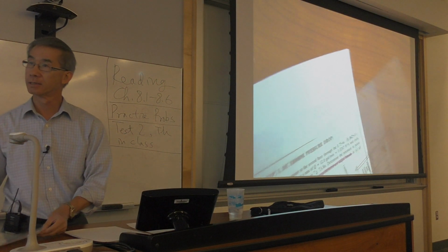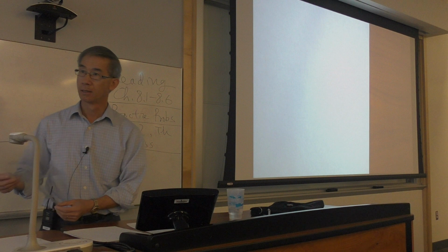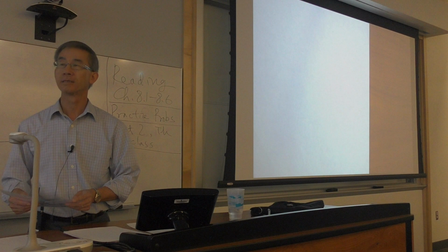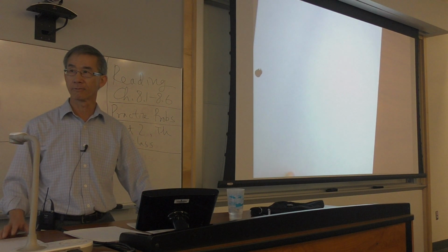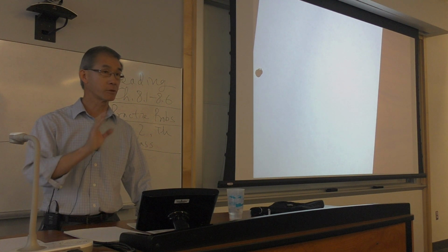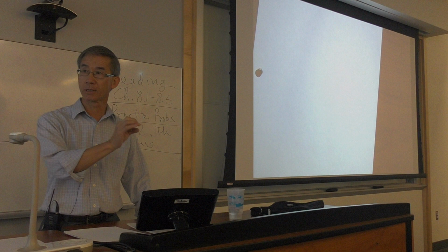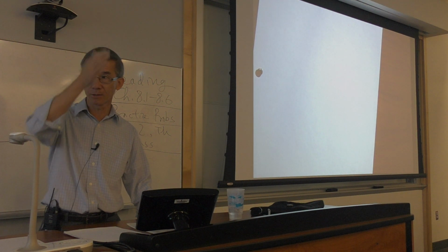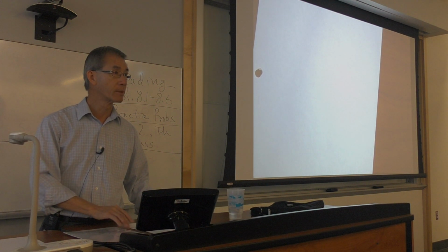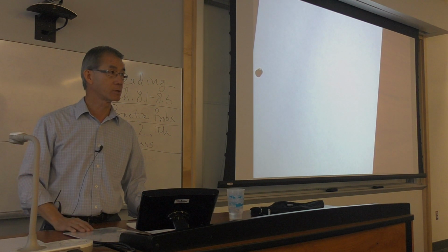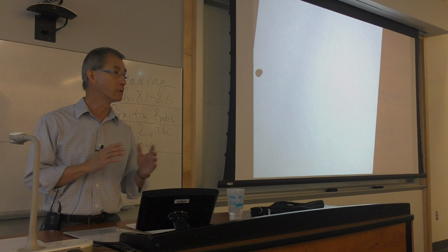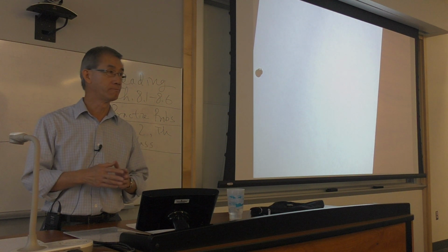Questions? Yes? When you're looking at the actual nozzle where the water's going to come out, you have to take into account the minor losses because it's the nozzle. That's correct. And the velocity change. That's correct. Very good observation. At the very end, you have a nozzle that's a K, plus you are also adding kinetic energy from a 3/4 inch pipe to a 1/2 inch pipe. So that sudden drop has two components: minor losses plus the kinetic energy. Yeah, very good. Right. So are you comfortable with that example? Just a very simple-minded walkthrough of all the components that will create pressure drop.